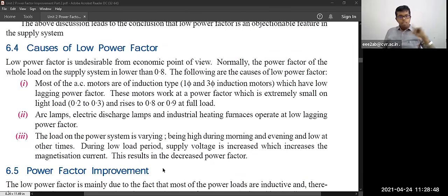So whatever power generation is coming will be like reactive power. Reactive power will be very high. In that scenario, your power factor will be very low. So always maintain a constant load. Don't go too high, or too low either.